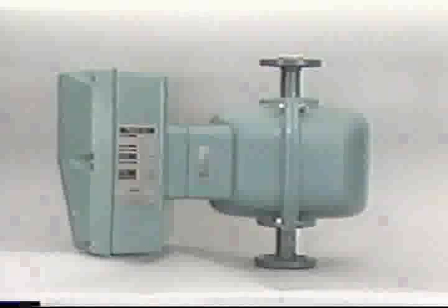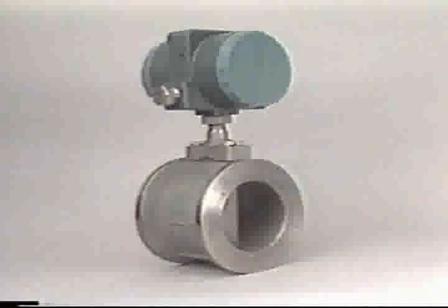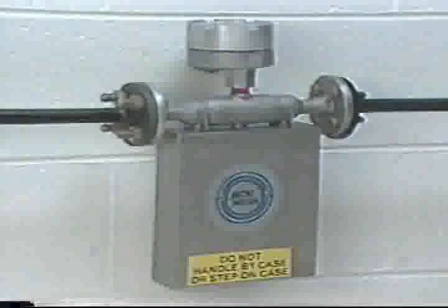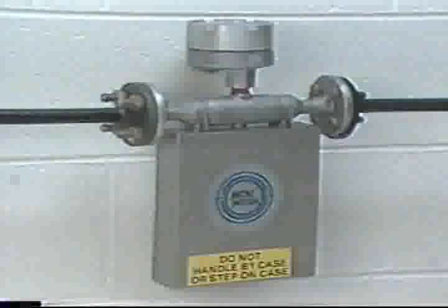Differential pressure transmitters are often used in conjunction with differential producers, like orifice plates and venturi tubes, to measure fluid flow. The flow of conductive liquids and fluids that contain solids or particulate matter are typically measured by magnetic flow meters. A vortex shedding flow meter can also be used to measure fluid flow. And mass flow meters, like the smart mass flow meter here, can directly measure the mass flow of gas, liquid, or steam. Now, let's look more closely at one of the many methods used to measure flow, the differential pressure transmitter.